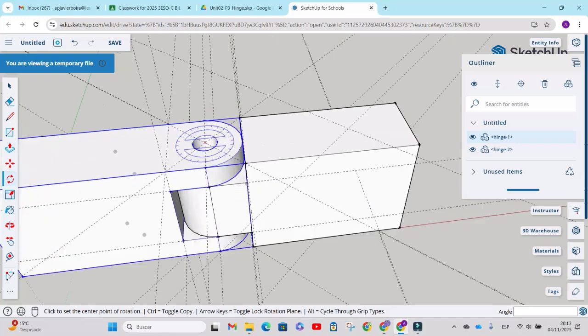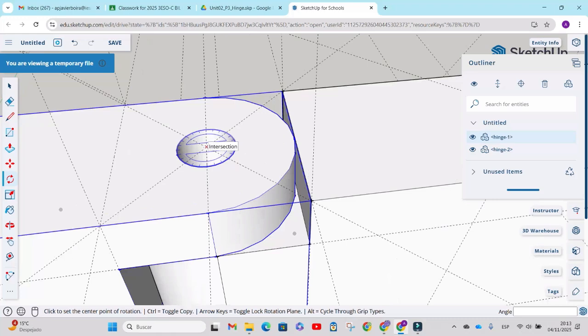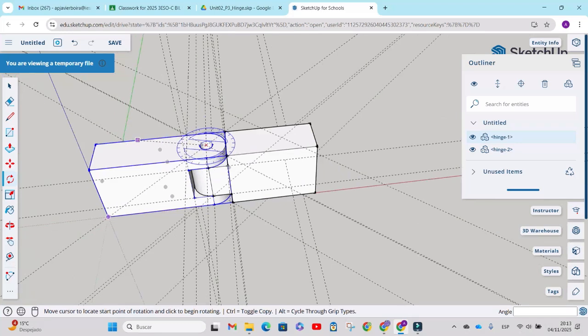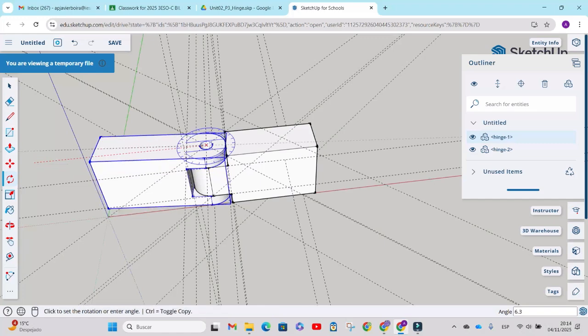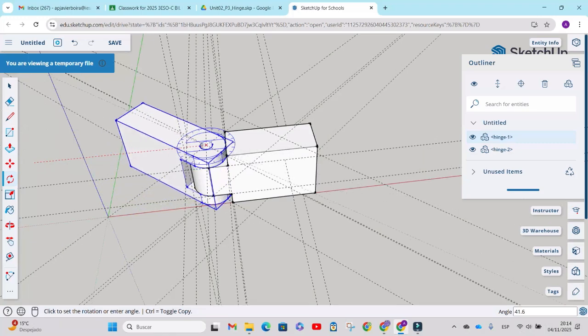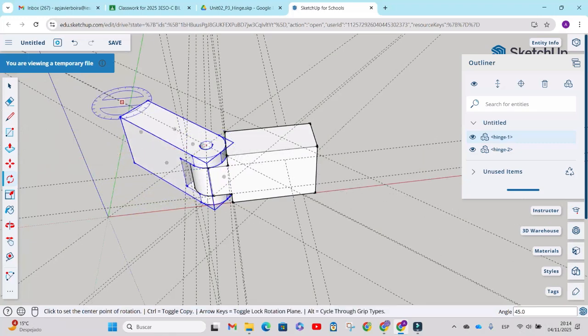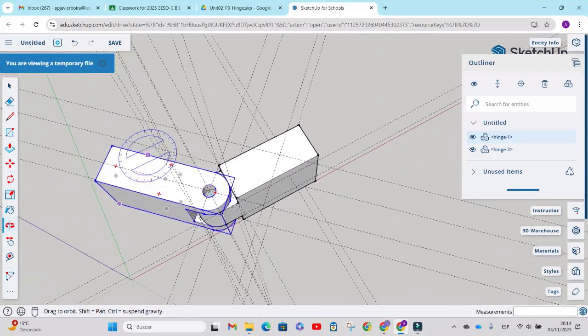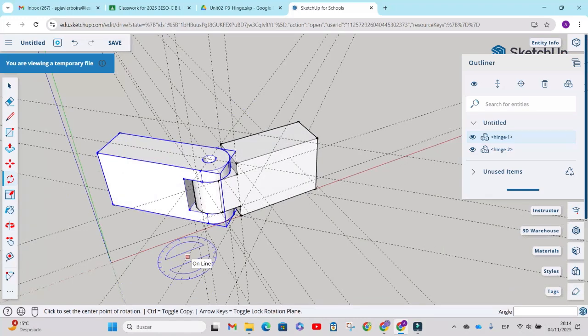Use the arrows and attach it to the center. After clicking, you move it along the hinge one part, you click again at the end and you rotate the hinge. You see, now you have it rotated and that's the final outlook.